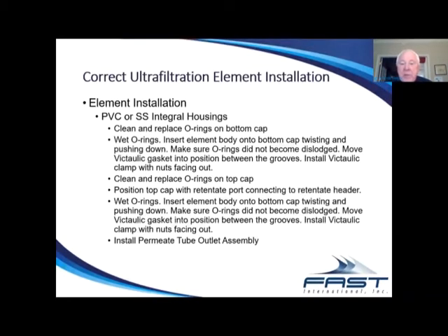And then clean and replace the O-rings in the top cap. Again, position it so that the retentate port on the top cap is feeding the retentate header, is connected to it and aligned with it. Wet the O-rings, insert the body, twisting again, making sure you don't disrupt the O-rings, and install a permeate assembly. Next.